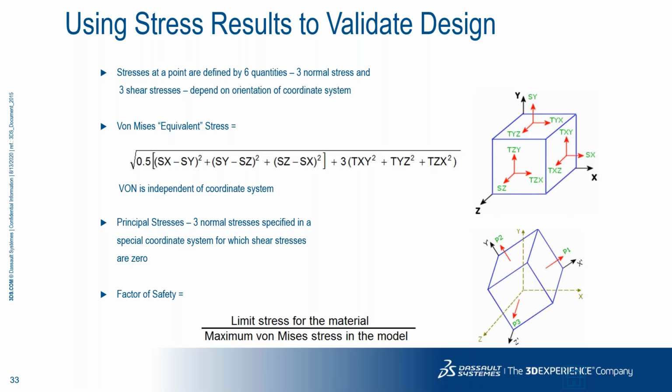In case of an assembly, when different yield strength materials are available, we can also use the factor of safety plot, which will help you to maintain the factor of safety of each component, which might be 1.2, 1.3, or it may be 4, 5, as per the criticality of that component and how the component will work.